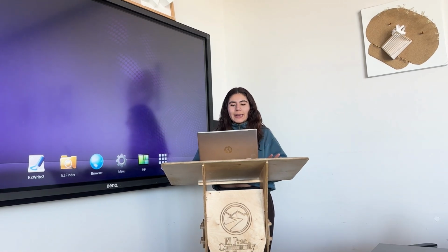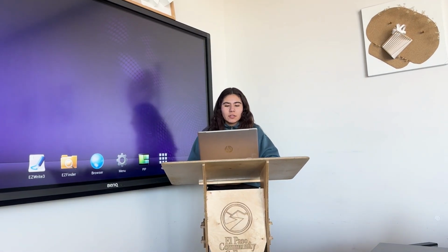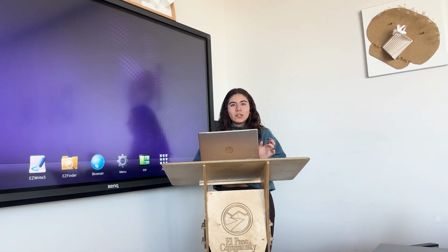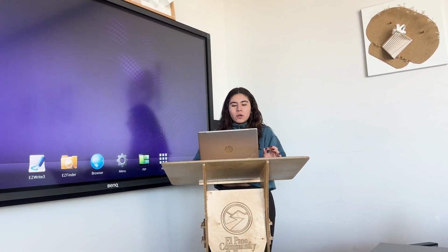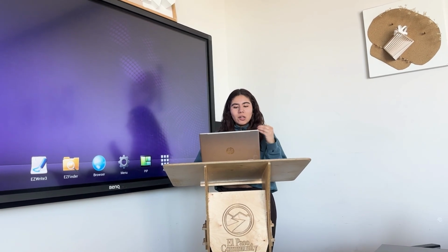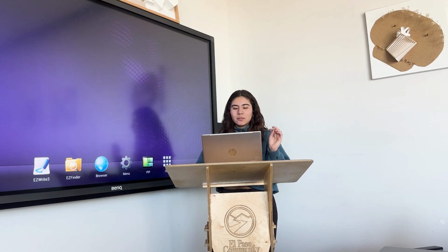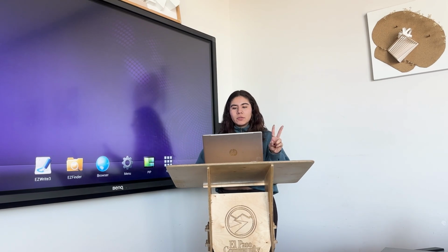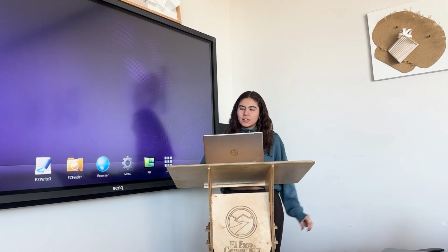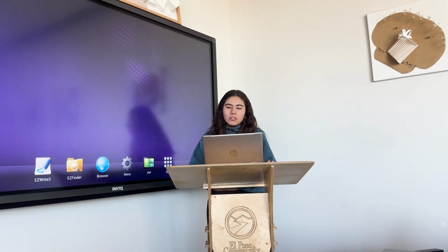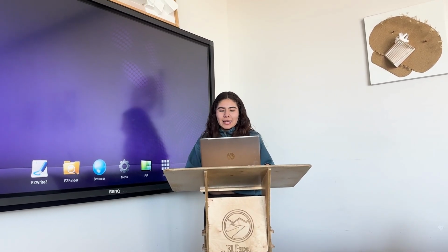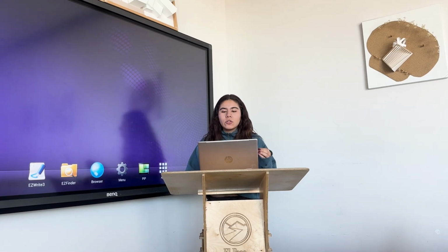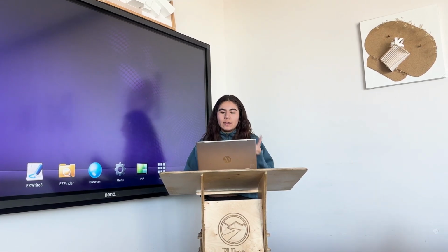So there are 3 different kinds of movement joints that are used in masonry, right? So we have the expansion joints, which are breaks in the material that can close or open to accommodate expansion and contraction due to changes in moisture content, temperature, structural movements, or other effects. Control joints are intentionally created planes of weakness that can open to accommodate shrinkage in masonry surfaces, and it's usually during initial curing.